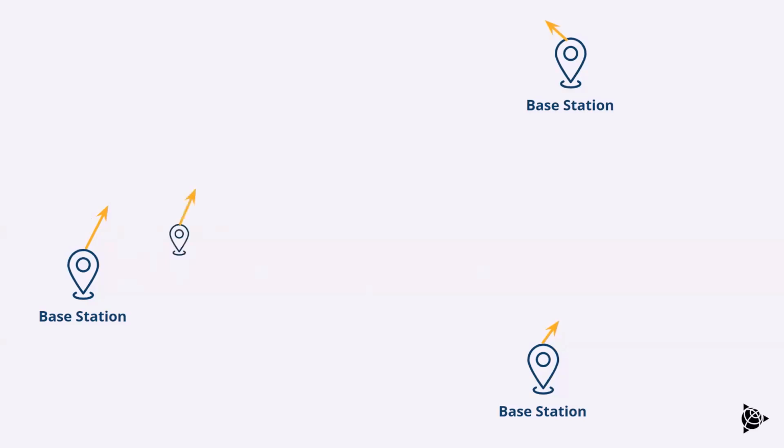So what that looks like is if we have a rover unit, it's going to essentially have a weighted vector depending on what base station you're close to. I know the math is a lot more complicated than this, but in simple terms, if we have a rover unit close to one of the base stations, it's going to pull most of the error correction from that base station. Same if you move it to the other base station, so it's going to have more of an error vector weighted closer to the other base station.